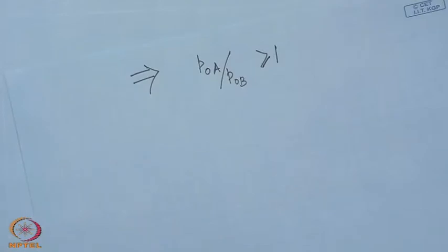This of course holds for any gas, even though it is derived for a perfect gas, the result is valid for all types of gases. That is, an increase in entropy at constant stagnation enthalpy will be associated with a decrease of stagnation pressure.